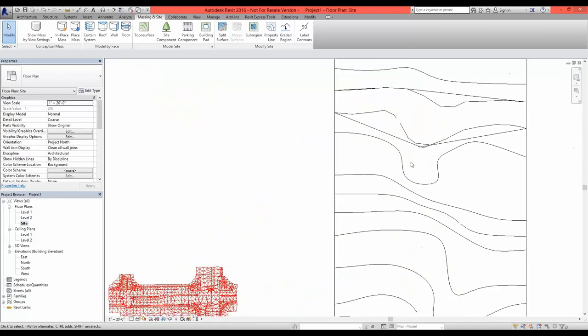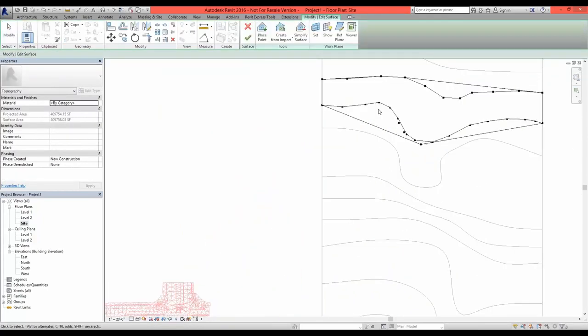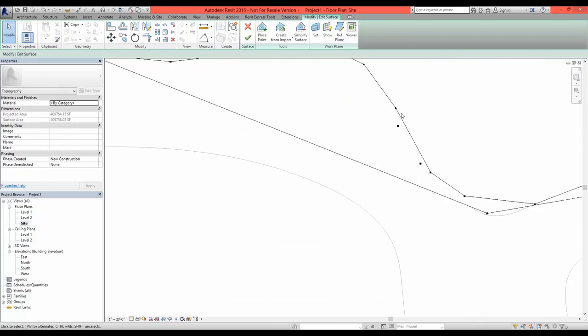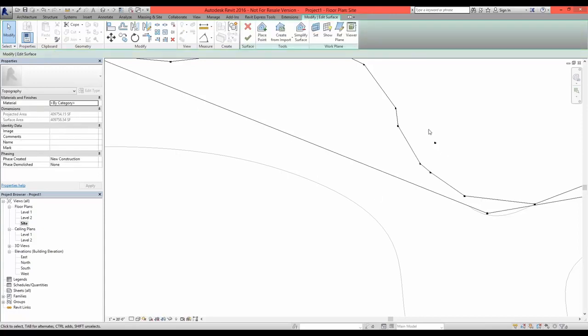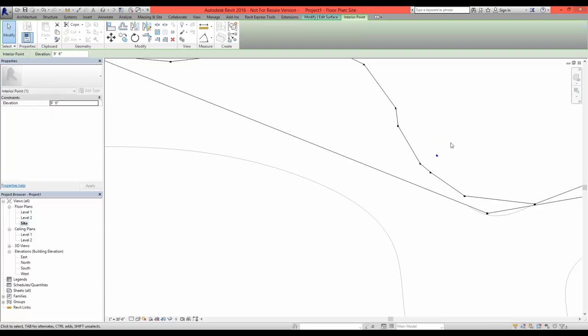And you'll notice that even in our Revit file, like I just pointed out, sometimes we have them placed together correctly, but Revit will just ignore you and draw a line across these two points that we're not intending for them to be drawn across. In those cases, we have to manipulate the model and add other values. So if I put another point behind this and call it 9'6", now even though this point is floating in space, we're being more explicit about what we want from Revit. And so now it starts to recognize those other points.